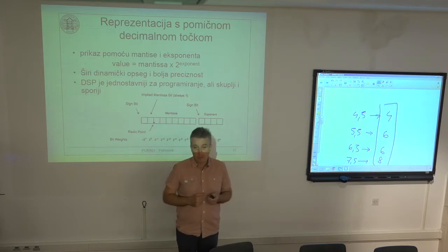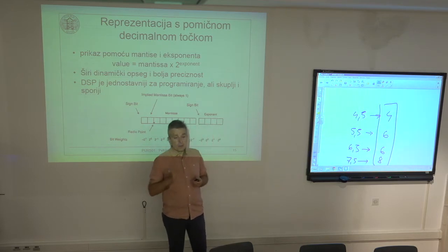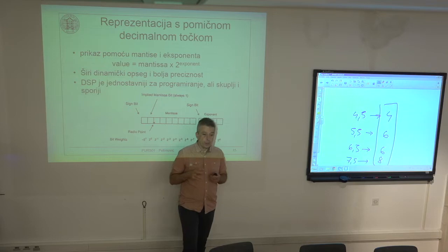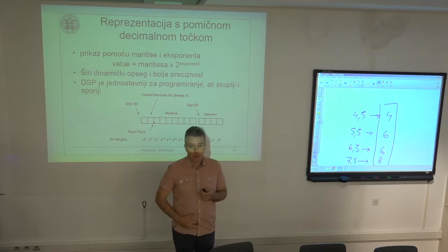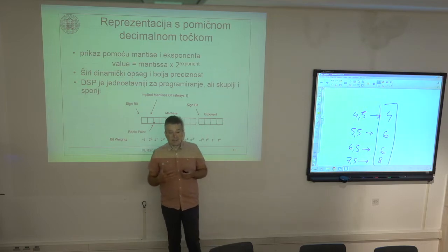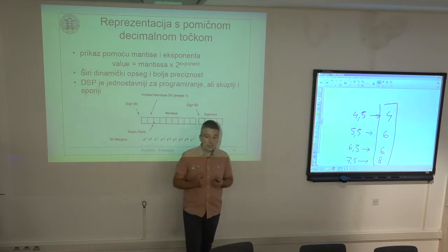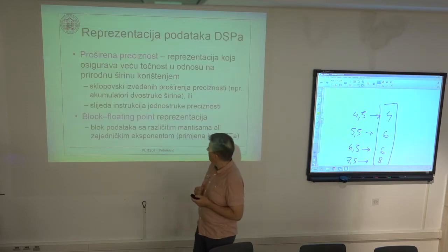That is the reason why fixed point implementation is preferred if you want a power efficient implementation of a DSP algorithm. If the algorithm can be adjusted and implemented on a fixed point architecture, it would always be more energy efficient than the floating point version.